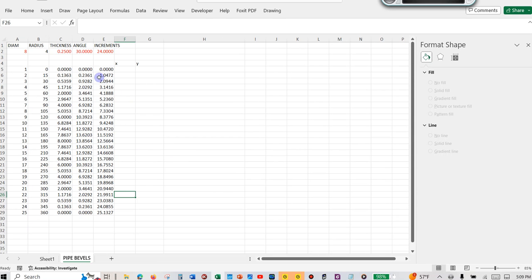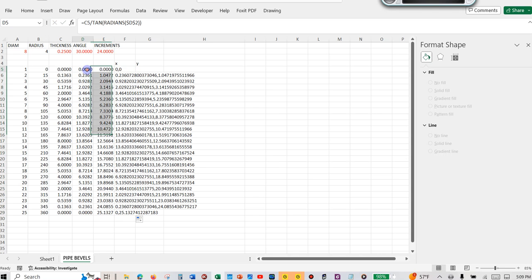So now I've got this bay, so I'm going to tell you what, we could go equals, concatenate for this, and open a quote, comma, close quote, and this. And then now I've got enter, and I've got my XYZ coordinates, I can do that. And I think I'm going to change this, equals round, and then there, comma, we'll go 3 places, enter.